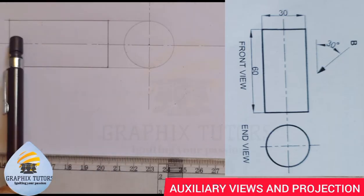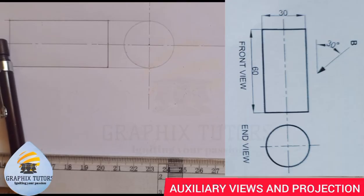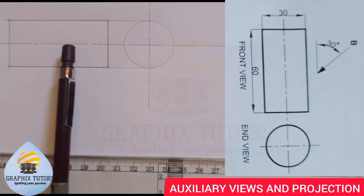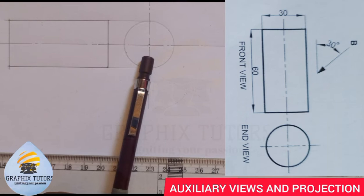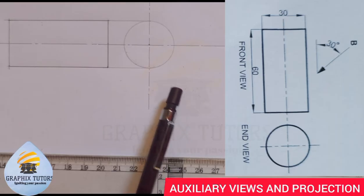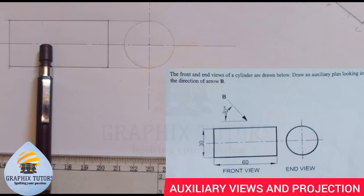Now because of the way it is lying, you're seeing this as the end view and this as the front view. But if you turn it the way I've turned the right hand side, this will change. It will become the front elevation, which is the front view, and here will still become the end view. So what they want us to draw is the auxiliary plan, meaning that we're going to project the front view. Are we together now?